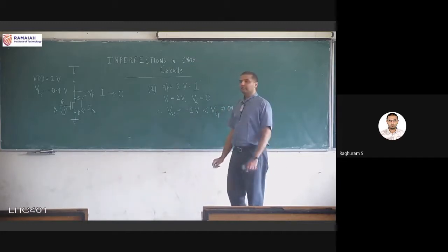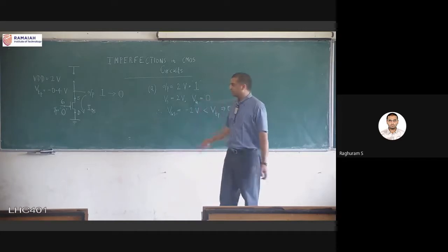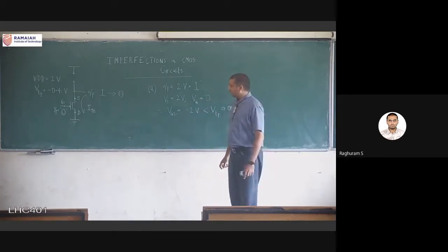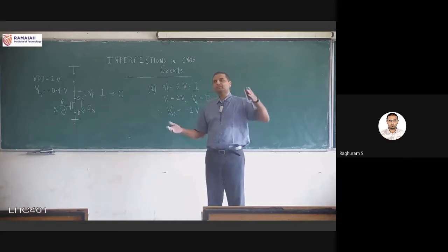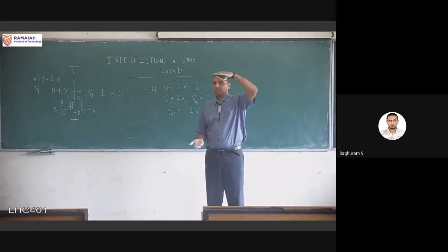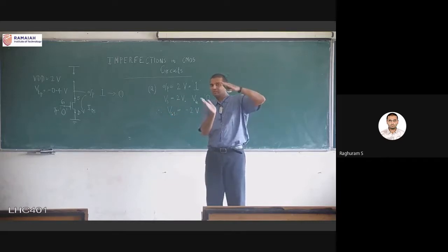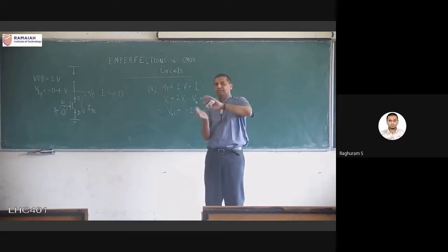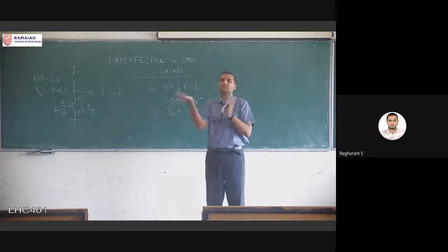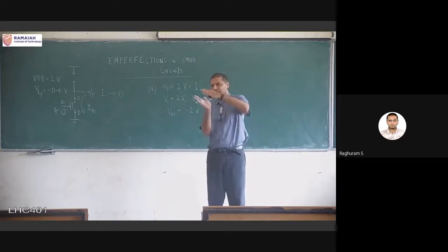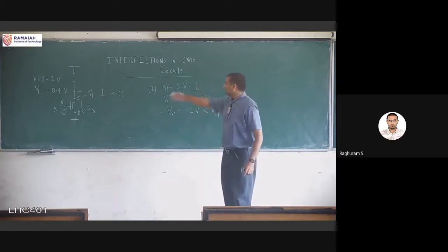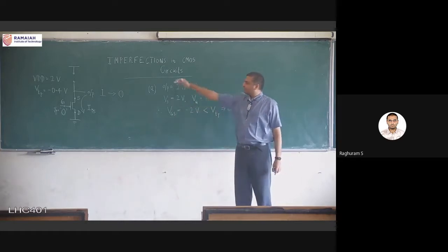Okay, and let's also find out the region of operation, because this is a good exercise with the PMOS transistor. For both NMOS and PMOS, remember that if the drain and source voltage difference is high, generally it means it is in saturation. If the drain and source are at close levels, maybe not. Greater than, lesser than doesn't matter too much, because in NMOS they need to be greater than, in PMOS they need to be lesser than, all that is fine. But if the magnitude of VDS is high, it means they are in saturation. So by that analysis, if you see this diagram, drain source voltage is quite high because source is at 2 volts, drain is at 0 volts.